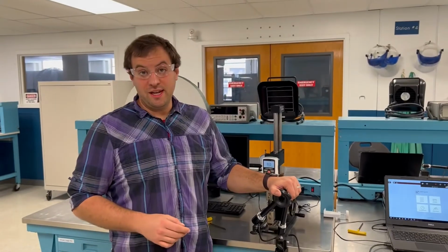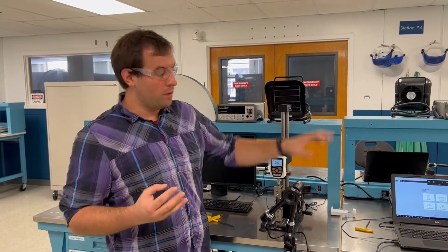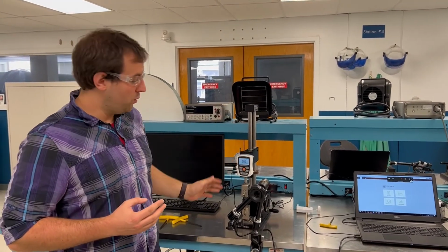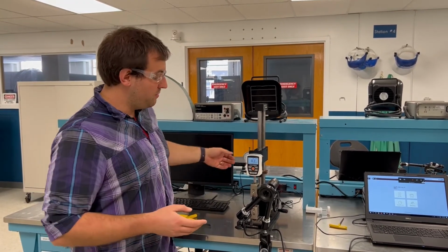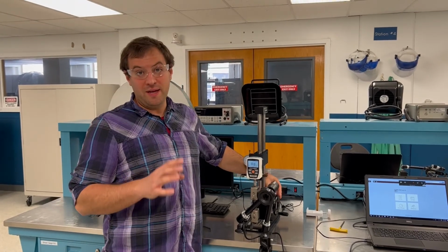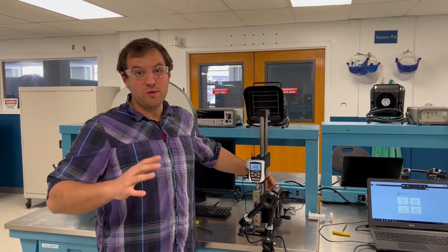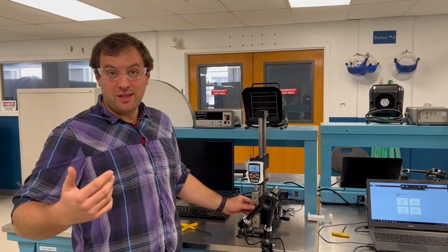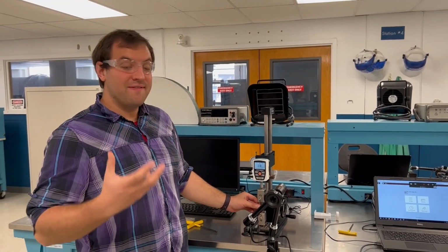Now that the system is set up and ready to perform data acquisition, you're going to want to break your group up into 3 people. 1 person to man the computer, 1 person to record the displacement as well as the force, and 1 person to turn the crank. These samples are much thicker than the samples we used in our prior labs. With that in mind, please make sure to not go over 150 pounds. Ideally, we'd like to keep it around 125. These samples are so thick that the poundage will actually increase relatively quickly, so I want you to be careful. Turn the crank very, very slowly.